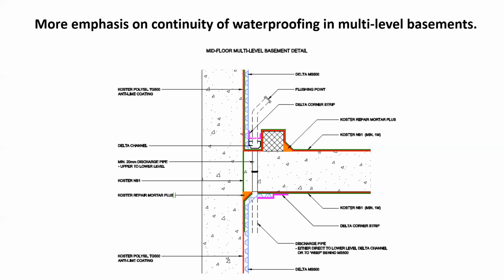A lot of basements in London and big cities, particularly big new ones, the Shard, things like that. These have multi-level basements. So consideration has been given to how we deal with water ingress in multi-level basements. So in other words, how do we get water that's come through the structure into a cavity drainage system, which is what you can see here. You can see the studded membrane, can't you, on the inside. How do we get that down through the intermediate floors and into a sump and pump system so it can be pumped out?